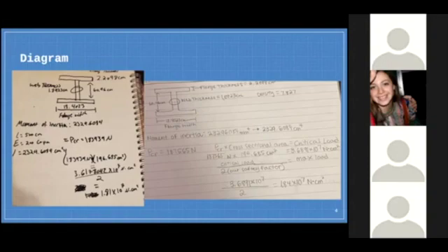When an external force is applied, this causes an internal shear force at the I-beam cross-section. This causes compressive and tensile forces, which result in a bending moment. And depending how the I-beam is supported and the reaction forces, this can cause positive sagging moments or negative hogging moments.